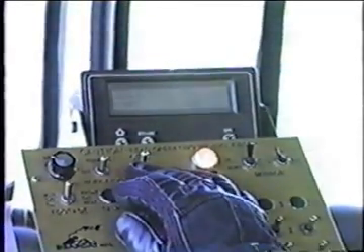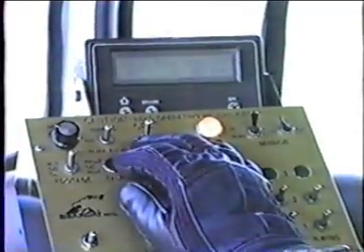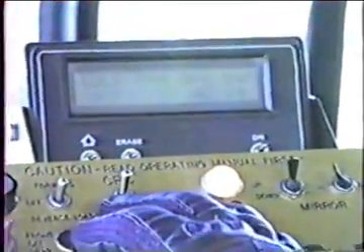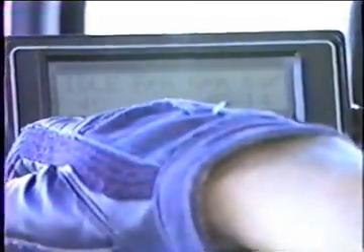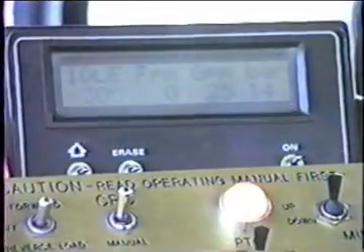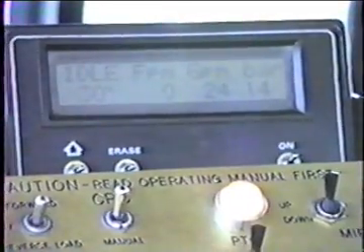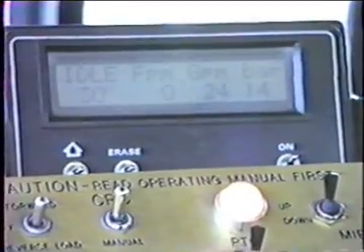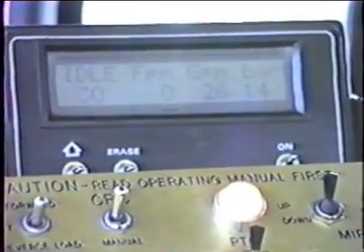Now it'll go to idling at whatever is in the idle window. There you see it idling at 40 gallons per minute, whatever we have set there. If we want to change that idle mode, we can do it while it's circulating there. If we want 30 gallons a minute, oh, I went on by, this thing goes fast. There's 30 gallons a minute. Now you'll see the GPM come up to the 30 gallons a minute that we have set in the window.